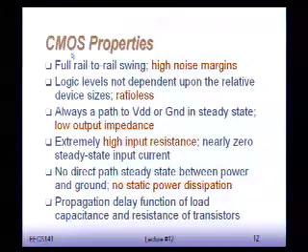All right. So let's summarize. What are the nice properties of CMOS logic that we've seen so far? So I think you've seen a little bit of pass transistor logic, although not really well worked out yet. But you will have seen that pass transistor logic is different from CMOS because it doesn't have full logic levels. You either lose a VT on the plus side or on the minus side if you only use either all N or all P devices, right?